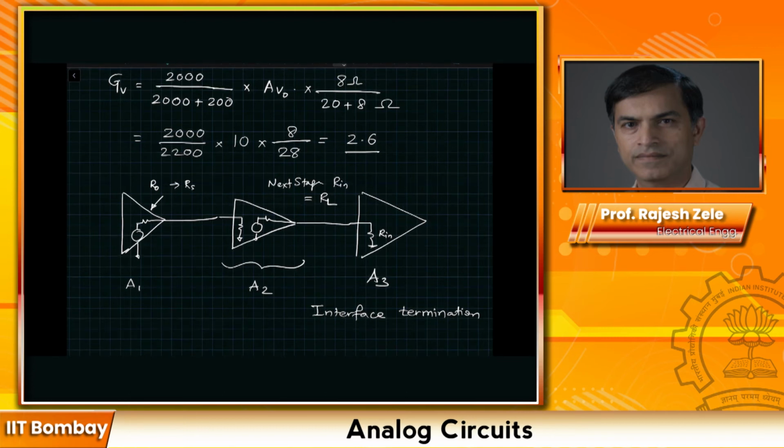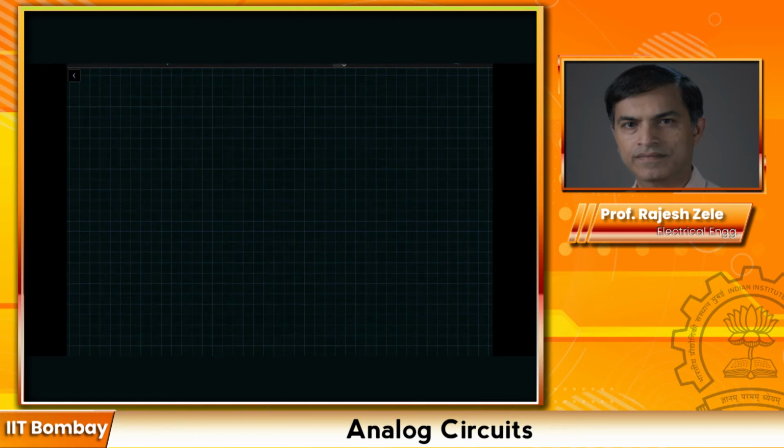So after this generic discussion of the amplifier, let's get into transistor level amplifiers. This discussion is going to become a segue for a variety of amplifiers we're going to discuss in the next few lectures. In this discussion, we are going to look at both bipolar and MOSFET amplifiers. The first amplifier we'll start off with is the common emitter, or CE, amplifier. As a starting point, we will start with an idealized circuit to understand the contribution from the transistor itself only.